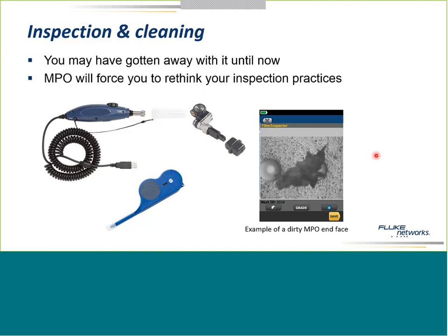And I got a good one yesterday. Look at that. I can't even see any of the core. That is just not going to transmit very well. The fiber just to the left of it, actually the core is still clear for the moment, but certainly I don't want to leave that piece of contaminant there. Possibly I'll break the fiber, which will be no fun.